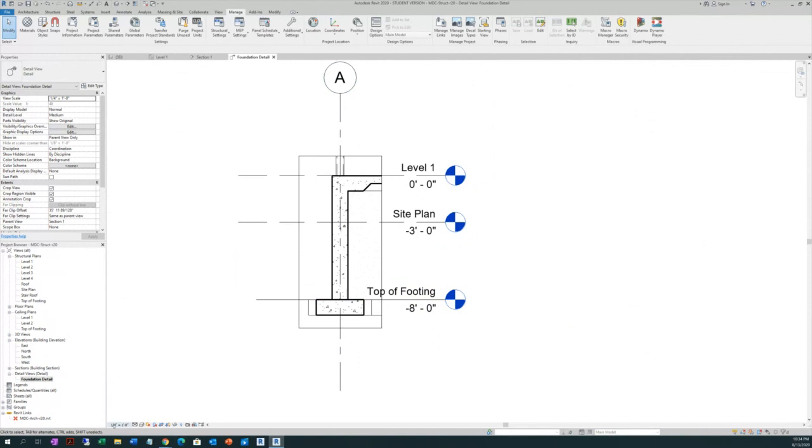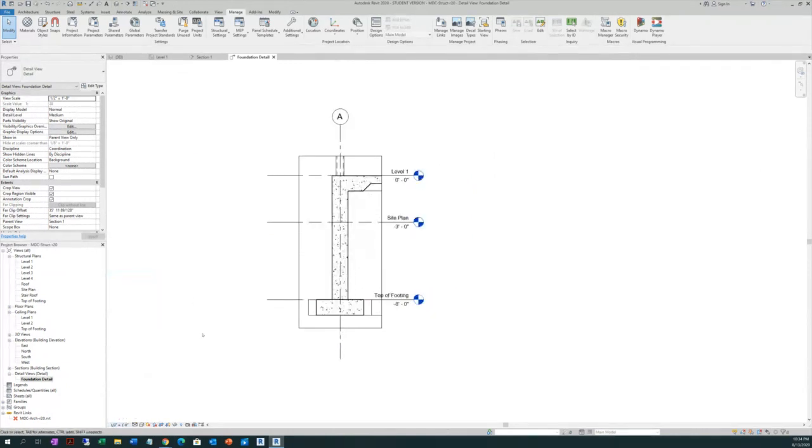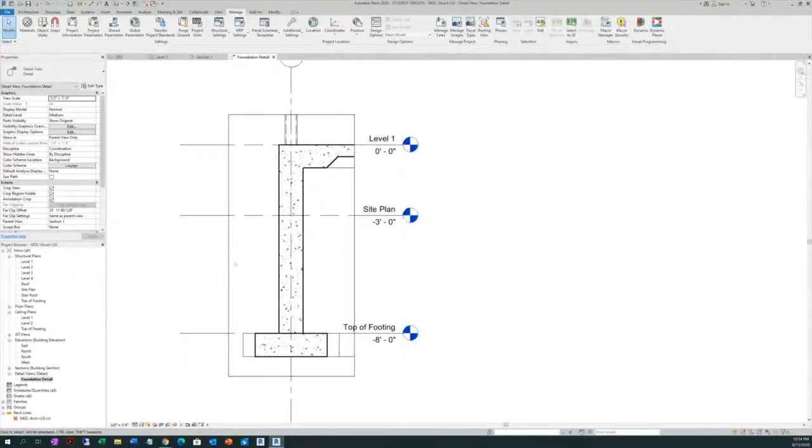You have something like this, and you want to have it in half scale. And then, one important thing. You see, you hover on that crop region, correct? Sometimes that drives us crazy. Why? Because between the space on the dash line and the continuous line, if you place a text there, it's not going to be readable. So keep that in mind.